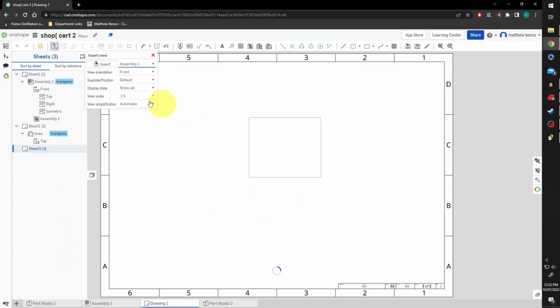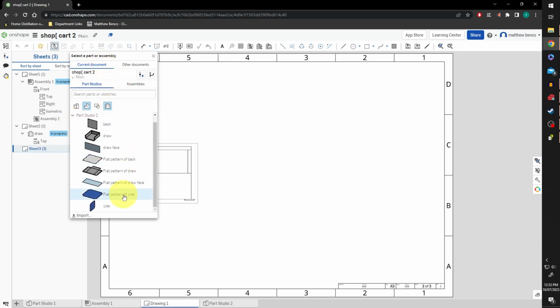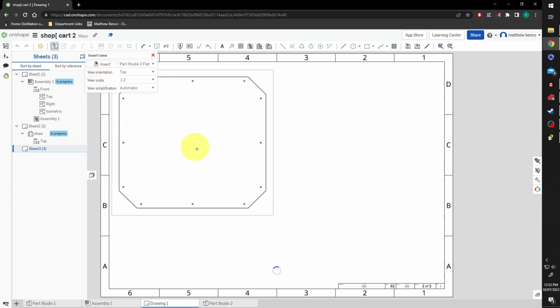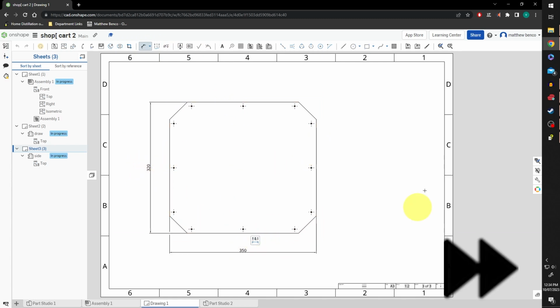We also need just to chuck in the development of our side. We're going to make that as scale 1 to 2. And we're just going to dimension this up quickly. I'm going to select those two and make it, there we go, 42. Put our dimension in for this as well. And we're only going to do it on the one because we're going to be able to assume that everything else is in the same place.